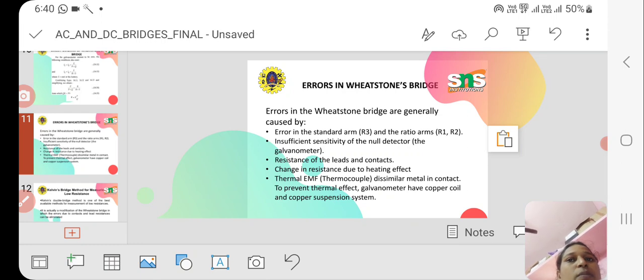So it is always preferable to measure medium resistance with the Wheatstone bridge, as it is not suitable for high resistance measurement. This is because in case of high resistance, the galvanometer is not sensitive to imbalance. Also, the heating effect due to the current in the circuit unnecessarily changes the resistance employed in it.